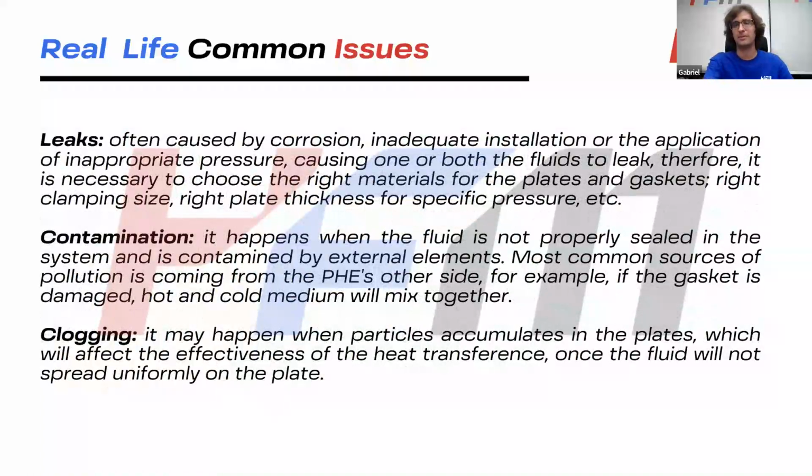They can also be caused by inadequate installation of the equipment. Inappropriate pressure: as you can see here, we have the plates between the frames, and these bolts apply pressure so that we can seal the liquids between the plates. If you put too little pressure, it's not going to be able to keep the fluids inside, so it's going to leak. But if you add too much pressure, it can also damage the gaskets, which is also going to generate other problems and even leaks as well. So there are some requirements. They are very specific and they need to be followed when making the installation.